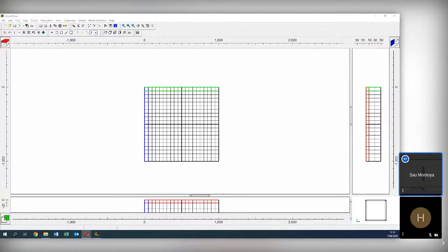For this exercise, there is something else. We are going to work with Modflow NWT. It's in Modflow 6, but we are going to work with Modflow NWT. Why? Because in this part, we are going to define the confined methods, and on Modflow 6 those have changed.